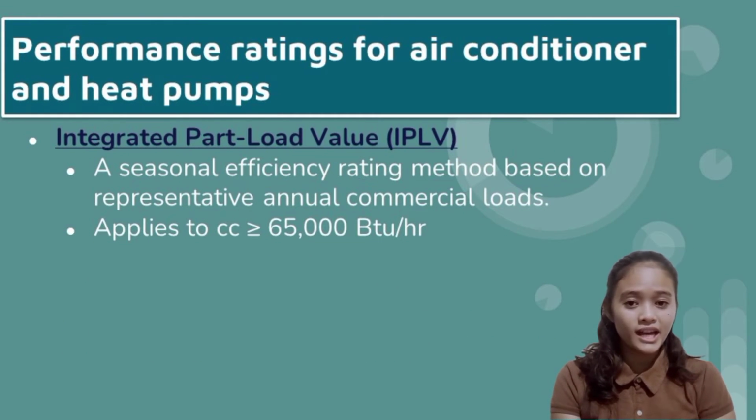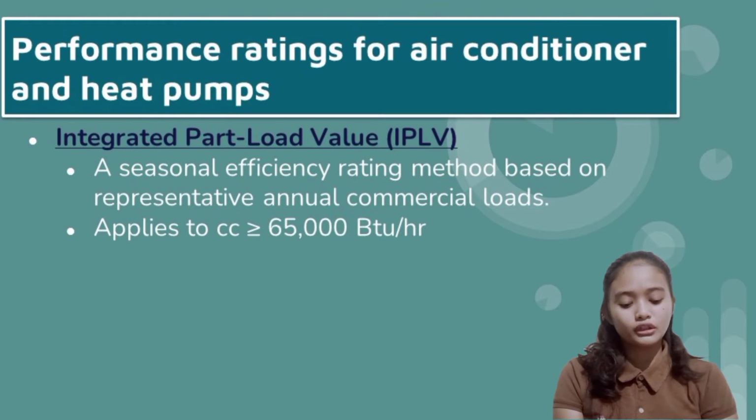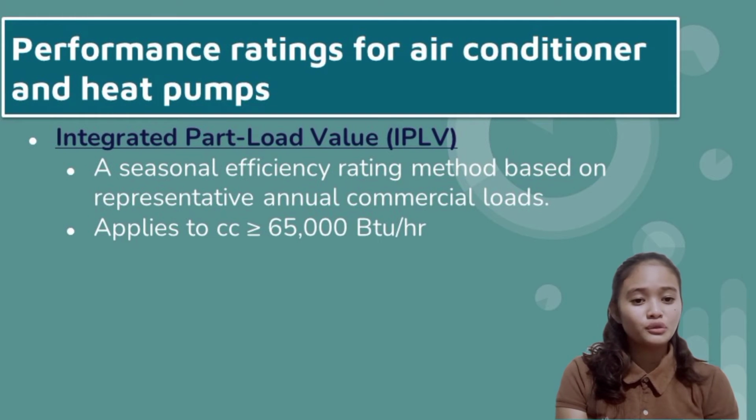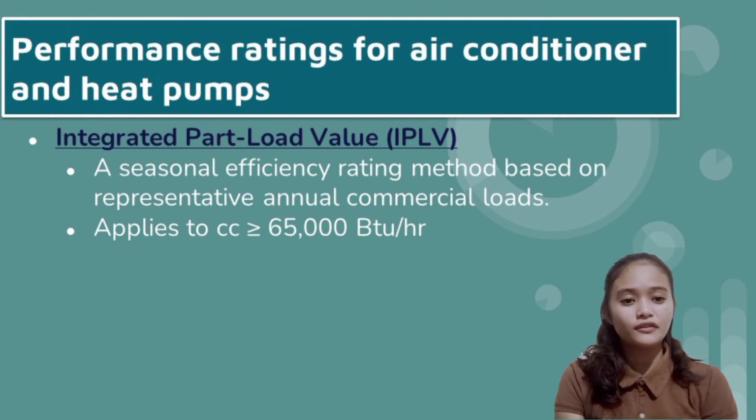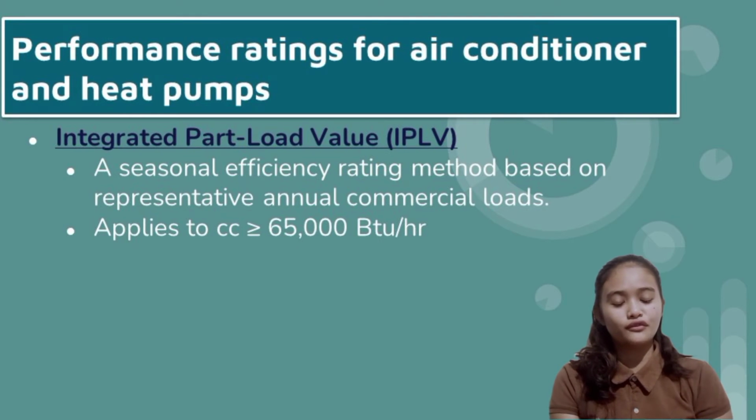Lastly is the IPLV, or the Integrated Part Load Value. This is a seasonal efficiency rating based on representative annual commercial loads. It only applies to air conditioners with a cooling capacity greater than or equal to 65,000 BTU per hour.